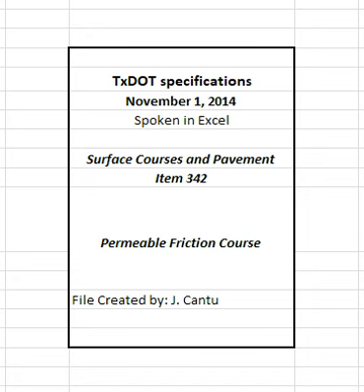2.5.2 Lime mineral filler. Add lime as mineral filler at a rate of 1% by weight of the total dry aggregate in accordance with Item 301, asphalt anti-stripping agents, unless otherwise shown on the plans or waived by the engineer based on Hamburg wheel test results. Do not add lime directly into the mixing drum of any plant where lime is removed through the exhaust stream unless the plant has a baghouse or dust collection system that reintroduces the lime into the drum.